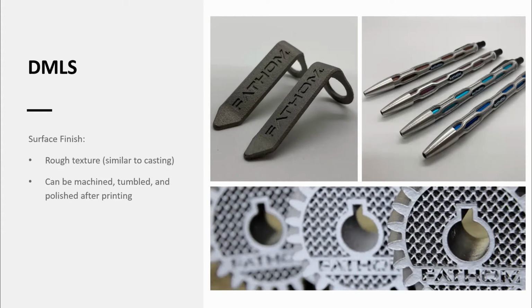However, there are a wide variety of post-processing technologies available for DMLS parts. These parts can be machined in order to achieve a smooth, high-tolerance surface, such as in the upper right corner. It can also be tumbled, shot peened, and polished in order to achieve a better surface finish.